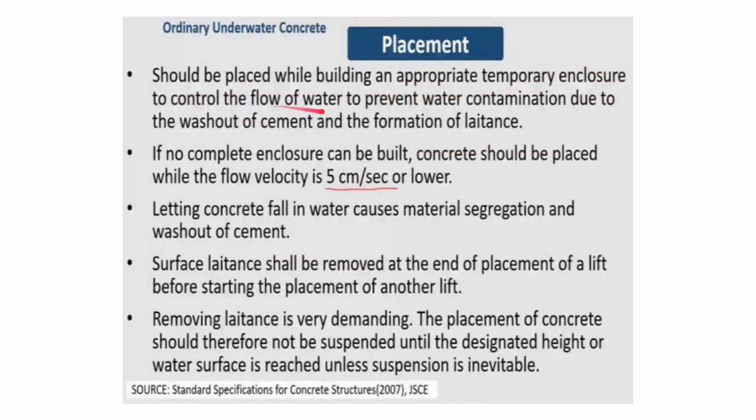Okay, to control the flow of water, to prevent water contamination due to the washout of cement and the formation of laitance. So segregation, laitance and washout, these are some of the important issues associated with underwater concrete.